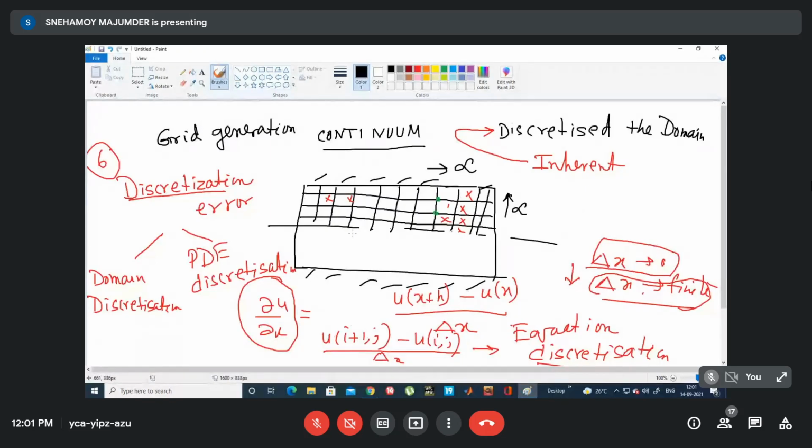Even if I have to do x, y, z direction, there is also the theta direction. This is r theta z, that is cylindrical coordinate, like flow going inside a pipe. So in the theta direction also I have to take the grid points. Supposing that the boundary conditions and geometry are symmetric, axisymmetric, so del theta is 0, no change along the theta direction. So I have to do the discretization along r direction, along z direction.